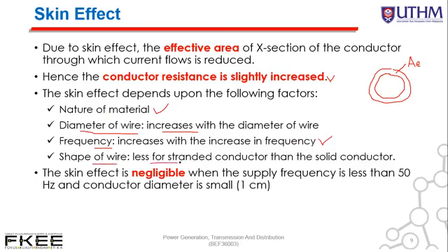Skin effect is less for a stranded conductor than a solid conductor. Let's say you have a conductor that is a combination of strands in a bundle form like this, compared to a solid conductor like this. The skin effect is less in this type of conductor when compared to the solid single-piece conductor.